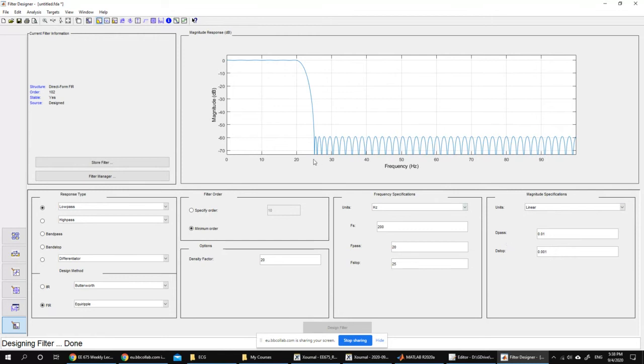So this looks like a good filter. You start with 20 here. This is the cutoff frequency. 20 looks okay. And at 30 or 25, you start the stop band. So at 30, you're sure that it will give you attenuation by at least 1/1000.